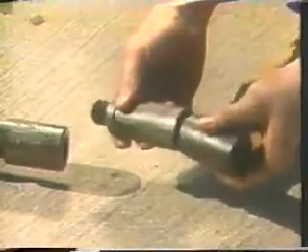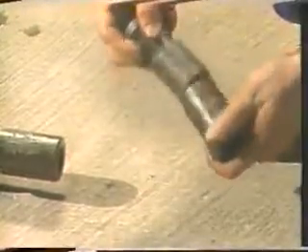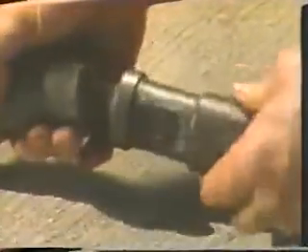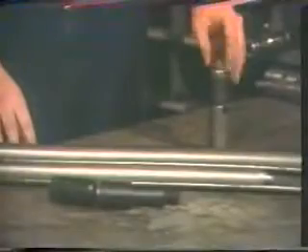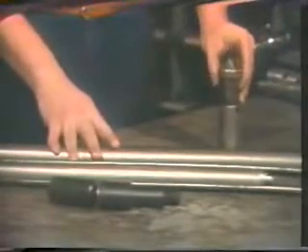Knuckle joints are used in the tool string to give the string flexibility. In crooked or corkscrewed tubing, this flexibility is important to allow the tools to pass through the tubing with a minimum of drag or friction between the tools and the tubing. At least one knuckle joint will normally be used directly below the jars in the tool string. This knuckle joint is used to allow the larger diameter tool or subsurface control attached below the joint to centralize itself in the bore of the tubing. These, then, are the components of the standard work string: the socket, the stem, jars, and the knuckle joint.